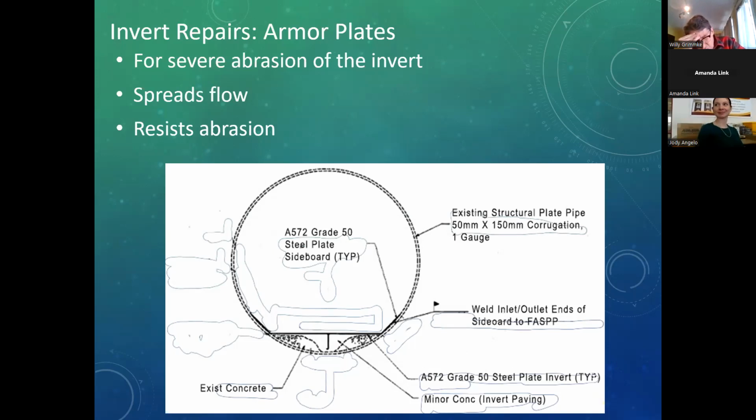What you would want to do with a larger than necessary culvert is determine your capacity, upsize it to the point where you can make sure that whatever you're going to be putting in the future would be adequately sized. And then let it go and monitor it. And then years from now, when it's time to reline, you slide a new one through.